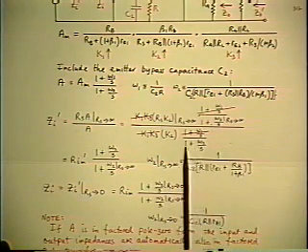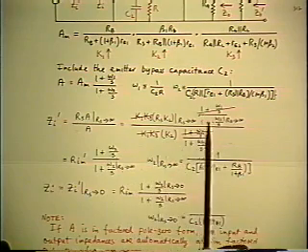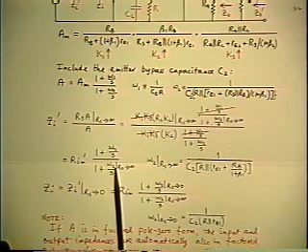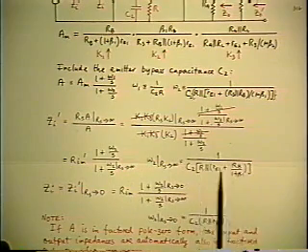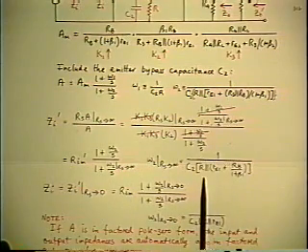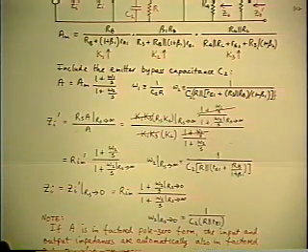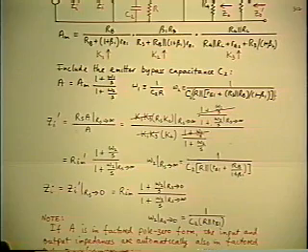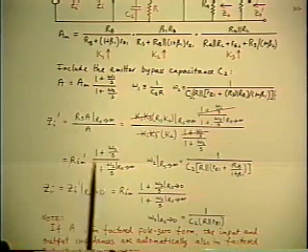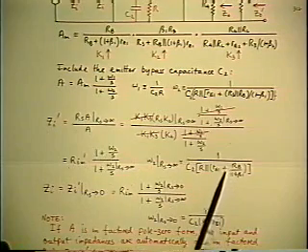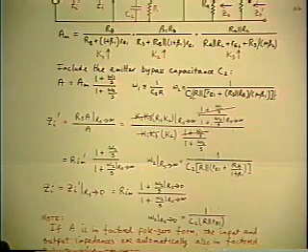So what happens is you get the original omega 2 factor in the numerator, and you get a new factor in the denominator involving a new corner frequency, but one that is obtained from the old one by taking the limit, which is easy enough to do. And you see, we've automatically ended up with the input impedance in factored pole zero form, because those factors were just dealt with one by one anyway.